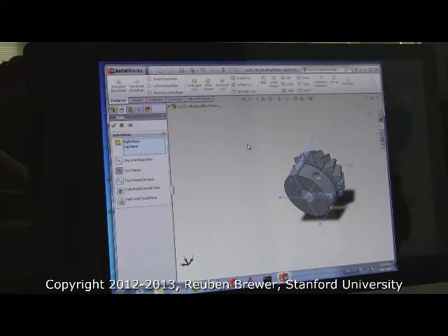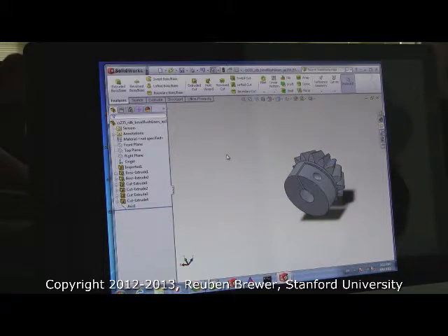And the axis will appear in yellow. See that? Click the green check mark and it persists. Okay, so this is useful for now, but if we put this in assembly, the axis shows up in the assembly. And now if we do hundreds of these, it's a mess. We'd like to keep it but not see it. So go ahead on the left hand side and click on axis, and you see this little glasses thing that says hide. Do that. And then do it again and do show. This is how you hide things without deleting them.